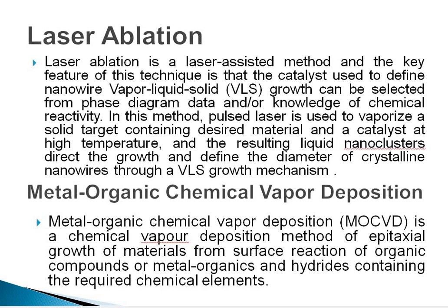Laser ablation is a laser assisted method, and the key feature of this technique is that the catalyst used to define nanowire vapor liquid solid growth can be selected from phase diagram data and our knowledge of chemical reactivity. Another method is metal organic chemical vapor deposition. It is a chemical vapor deposition method of epitaxial growth of material from surface reaction of organic compounds or metal organic and hybrids containing the required chemical elements.